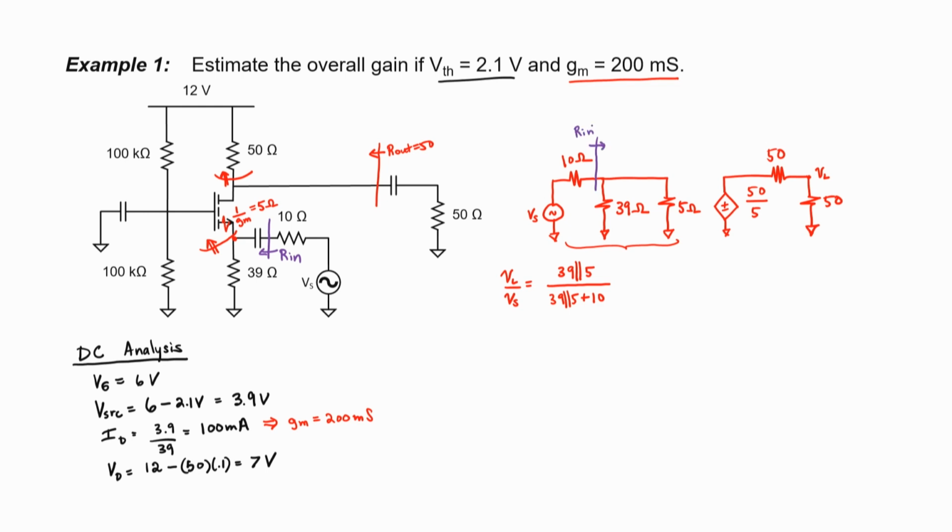And you might recall that for an amplifier, we typically want the input impedance to be as large as possible, but that's not what we have here with the common gate configuration. This input impedance is small because it mostly depends on 1 divided by the transconductance. The larger your transconductance, the smaller the input impedance.